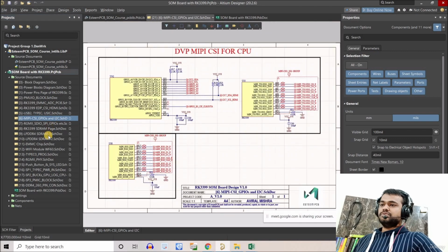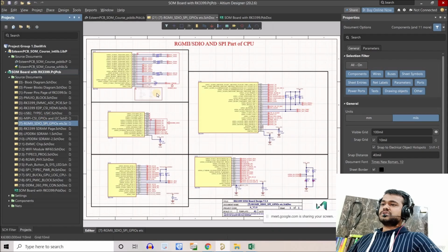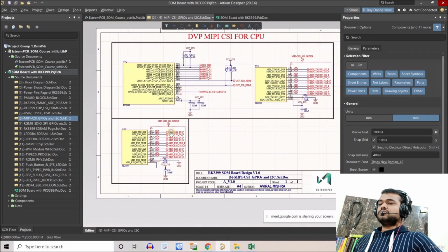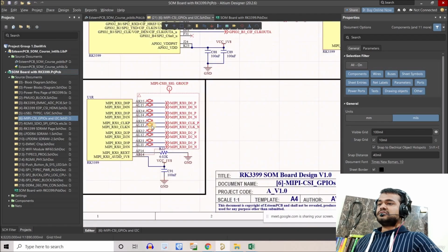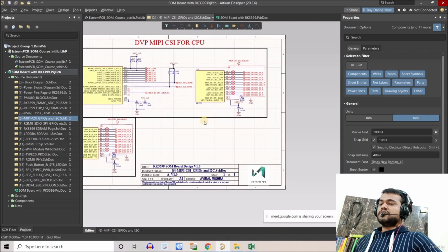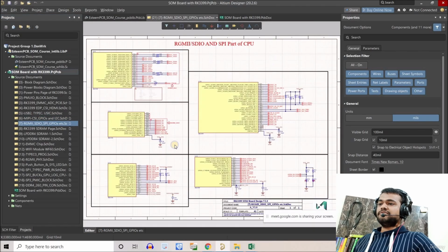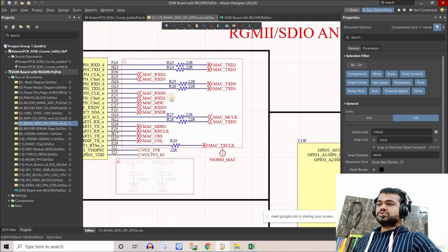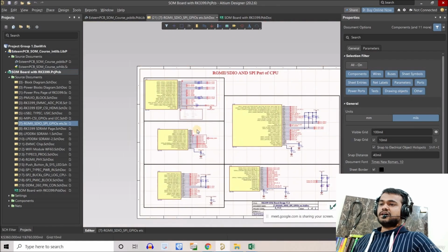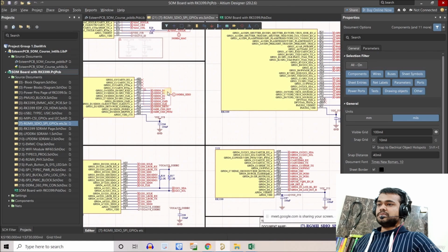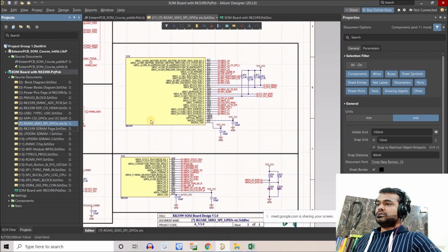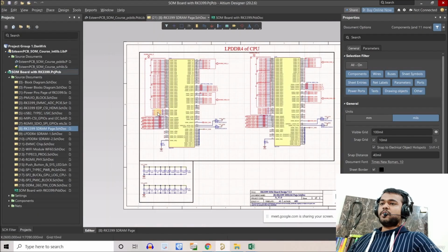If you go through each, for GPIOs, I2C, UART, we don't need any impedance standard, right? So I just leave those things. Apart from that, you'll see all the MIPI interfaces, or wherever we needed length matching and impedance, I've covered all of these and clubbed them into a net class or differential pair class. Similarly for SDIO, and yeah, this is important.